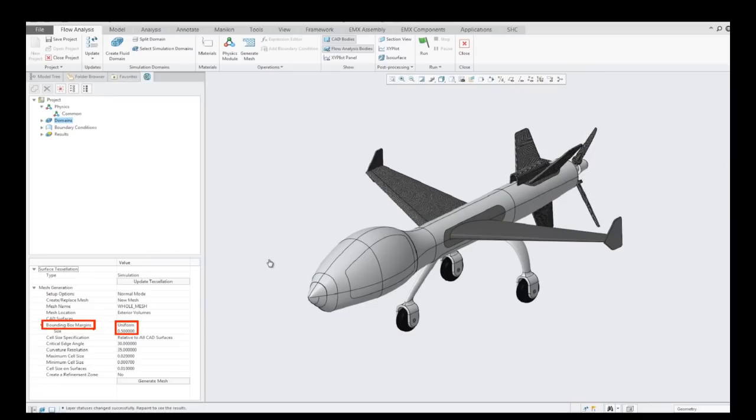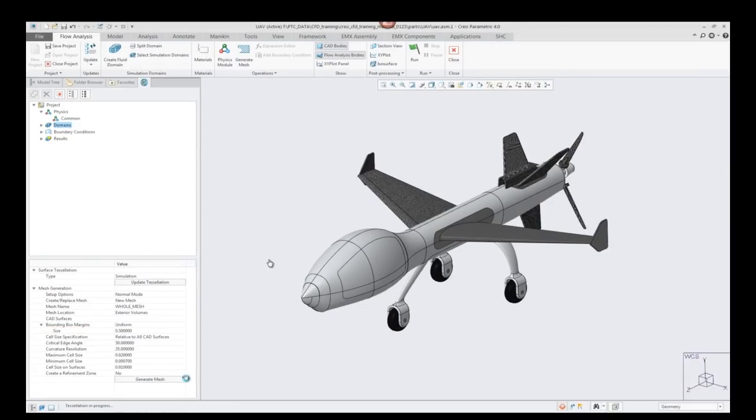And I'm saying that I want this hanger or bounding box to be 50% bigger overall than the thing that we're going to analyze. So if the plane is 5 meters long, it means that 50% we would get 2.5 meters in front, 2.5 meters behind. If it's 2 meters tall, it means we would get 1 meter above, 1 meter below, that sort of thing.